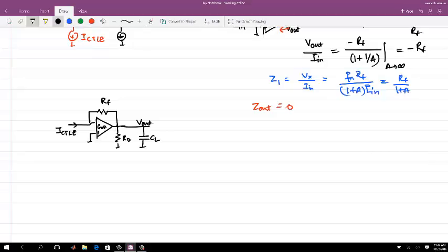So that will basically come as a secondary. Right now we have just realized that at the input you are having a very low impedance Z1. If you keep increasing the input pair size, then that pole will start becoming more dominant. But the thing is, CL is actually the much larger load in the system. To begin with, that's the assumption I started with. So this is I_RF.